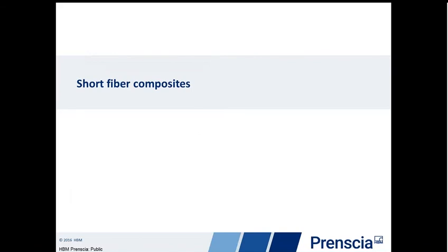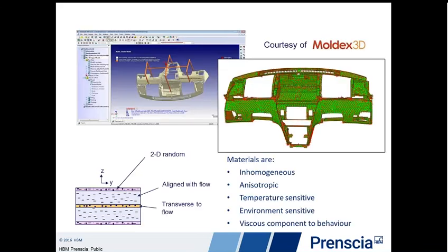In addition to strain life, we've applied vibration fatigue to our short fiber composites. In a short fiber composite analysis, I'm looking at a material that is many times just injection molded, where I have two components to the material. I'll have a plastic matrix and a reinforcement fiber, glass or carbon fiber. Because of the injection molding, the material becomes directional.